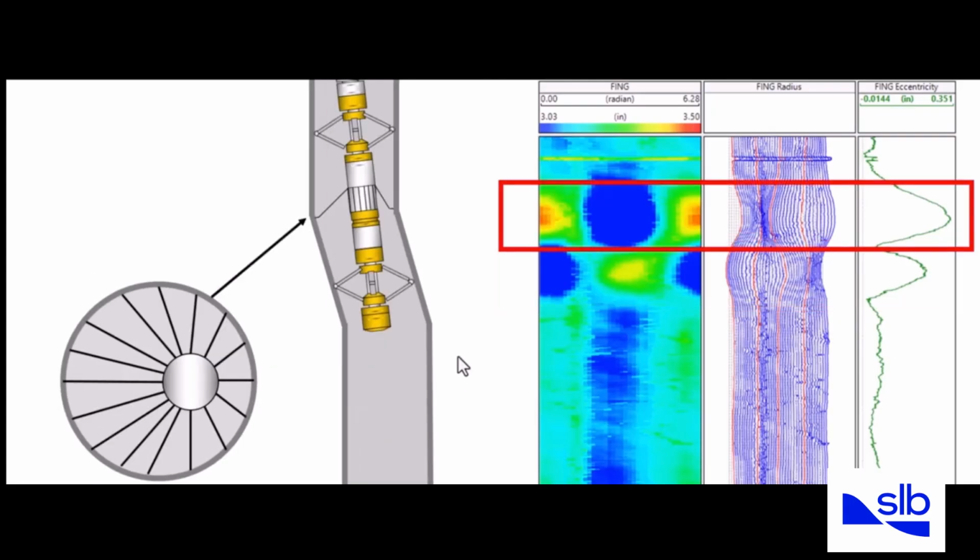As the tool string exits the deformed interval, the MFC tool will be pushed towards the other side of the pipe, and the orientation or direction of the eccentricity will change. Now we can see that the fingers on this side will open less than these other fingers, okay?